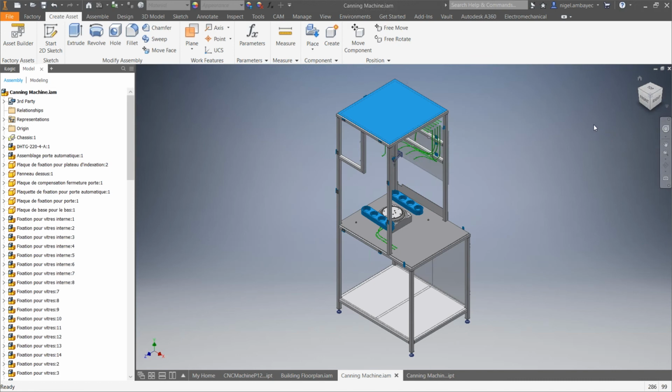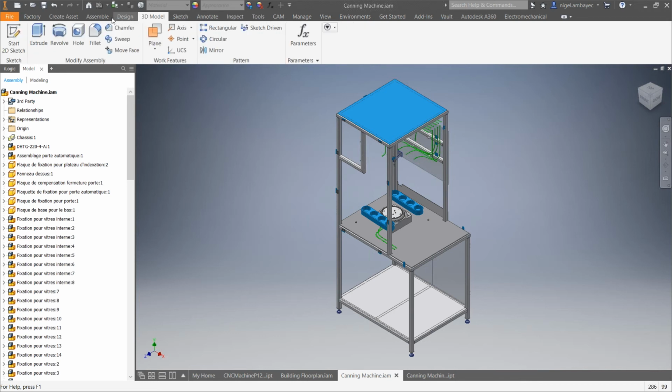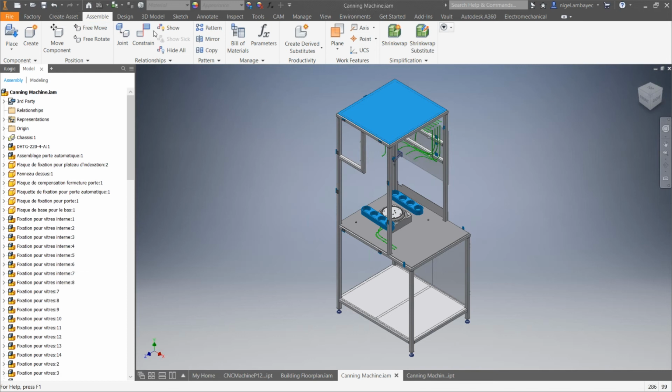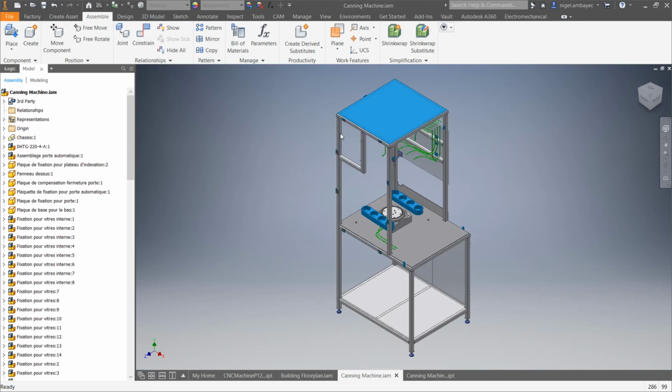And so myself and Javier, and I'm sure a lot of other people, do not suggest creating assets out of full assembly files. What you should do instead is convert this assembly and simplify it as much as possible. Part of that is either doing a shrink wrap or a derive of this. I believe it's in tools. Here it is, under assemble. Shrink wrap essentially takes this and creates a part file that is essentially the exterior of this file.